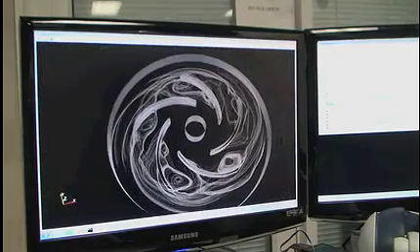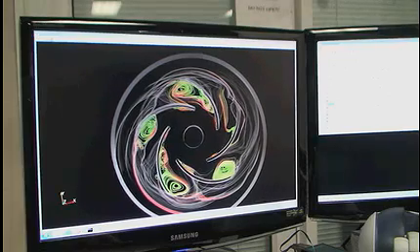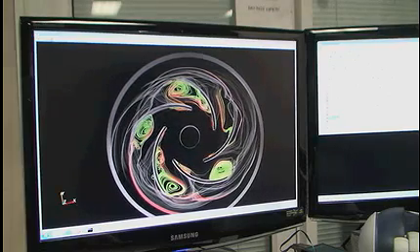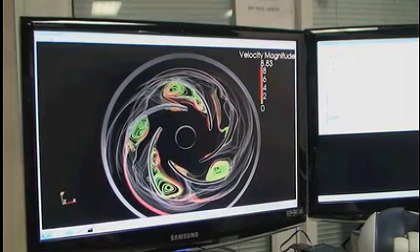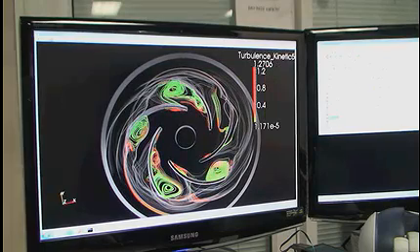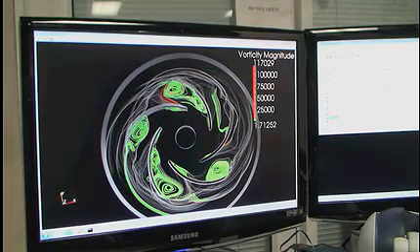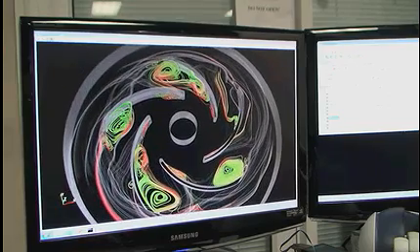The vortex structures can be colored by any scalar field provided in the given dataset. Here, the vortices are colored by relative velocity magnitude. For this dataset, the vortices can also be colored by pressure, kinetic energy, vorticity, and the computed winding angle. Our workbench allows the user to observe structural changes to the fluid flow by stepping through a UI time slider.